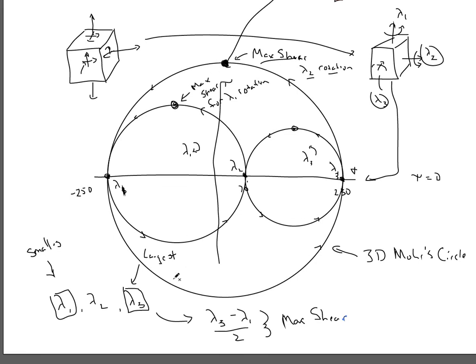But if you imagine something that's transversely isotropic or orthotropic, where our material properties are not the same in every single direction, you could have a failure shear for an off-axis rotation that ends up actually failing your material, right? So it could be really strong against shear in one direction, and if we align that with the max shear condition, we may not fail at this max shear, but we may end up failing due to these transverse shears here and here.